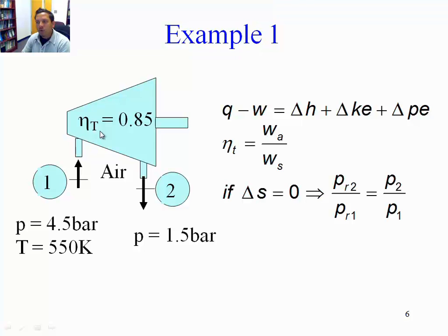And we know that this turbine has an adiabatic efficiency of 85%, meaning that due to the second law of thermodynamics, there are 15% losses in the process from inlet to outlet. 15% of work that is not going to be developed, basically thermal energy that is not going to be transformed into work due to the efficiency, or basically the presence of entropy in the system or in the working fluid.